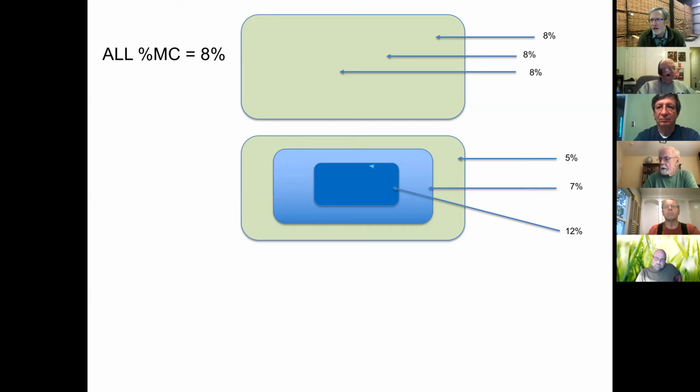And I came back on Saturday and it had moved. Well, what had happened? That piece was actually at 8%, which is exactly what he said it was. But the outside is down around 5, a third of the way in is around 7, and in the center it wasn't completely dry. So if we'd done an oven dry test, it would have said, hey, this is at 8%, it's ready